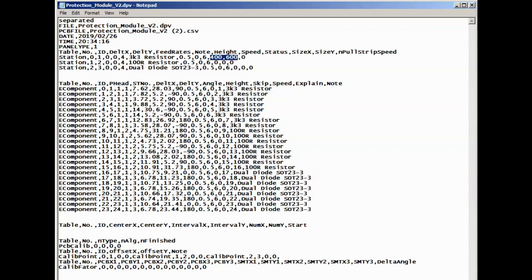Now, this information is taken from the CSV file, so in EagleCAD systems, as well as having the X and Y location for the particular components, it also has additional pad information for the components. And a lot of other CAD systems can do that, but because some don't, I've set this to ignore it. And a value of 0 means ignore the size of the component, just check its orientation. The information is taken by looking at the X and Y value of the components, and then the software, when you import the file, uses the pad information for the particular component to work out its size.